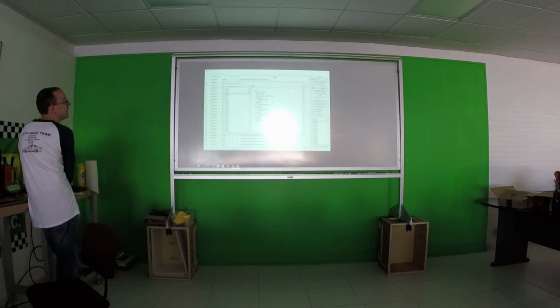And when you're looking for data, a lot of times what you're looking for is something that actually changes. So we can see this was always 40. This was always 0. We don't care about those. They probably don't mean anything. Data byte 2 here, though, went all the way from 0 up to FF, which is 255. So it has the entire range.